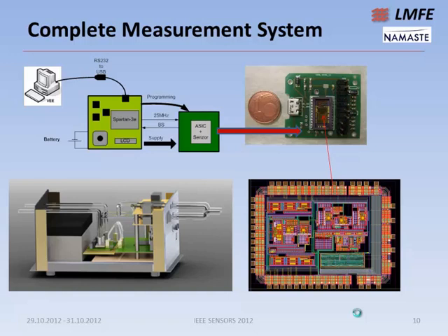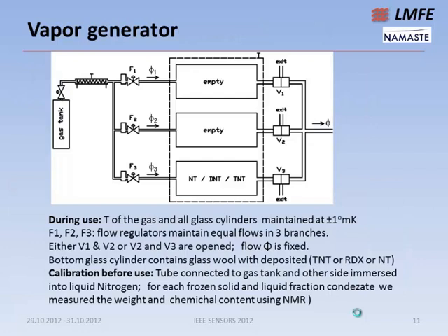Here is the actual analog chip. So this chip plus two pairs of sensors plus some external components is connected via USB to the FPGA-implemented DSP and to the PC via USB. And this is the whole system, which includes battery, our chip, some pipes, and piezoelectric pumps to be able to do the measurements.